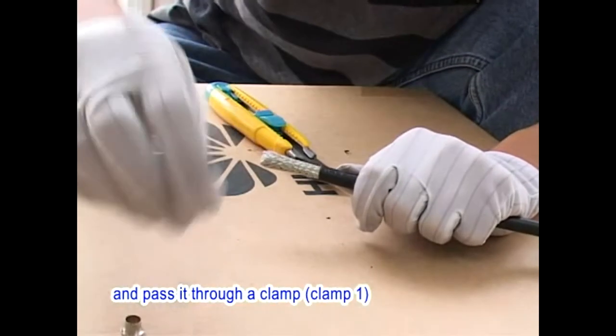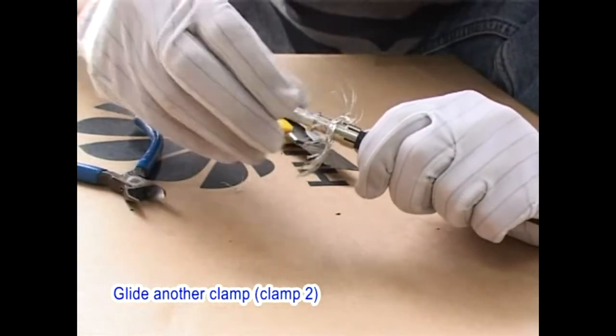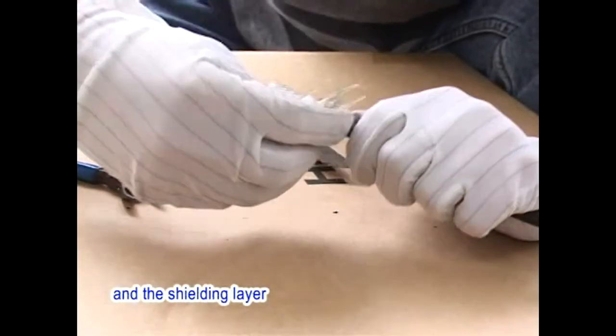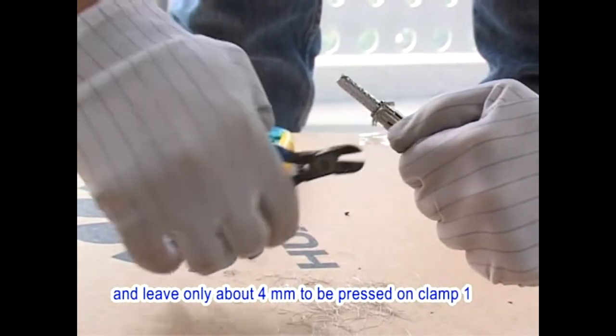Neaten the shielding layer and pass it through a clamp, clamp 1. Fold back the shielding layer. Glide another clamp, clamp 2, over the cable and fix clamp 2 between the insulating layer and the shielding layer. Trim off the surplus shielding layer and leave only about 4 mm to be pressed on clamp 1.